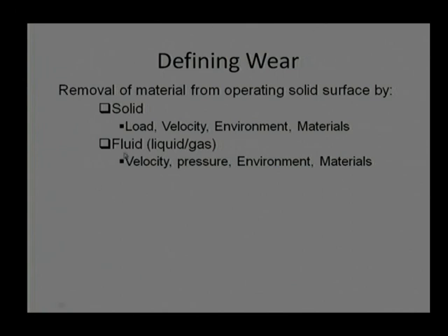When we treat wear by a fluid, we say that it depends on the relative velocity and the applied pressure or induced pressure. Here we do not use the word load, we use pressure because we know there will be a uniform distribution, while in the case of load there can also be a more concentrated load. So, that is why we use the word pressure here. Of course, the remaining two parameters will be the same, environment and material.